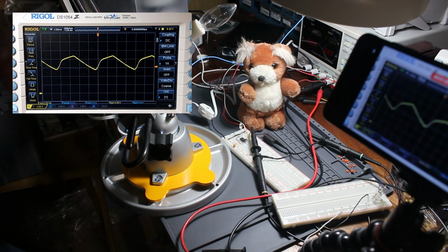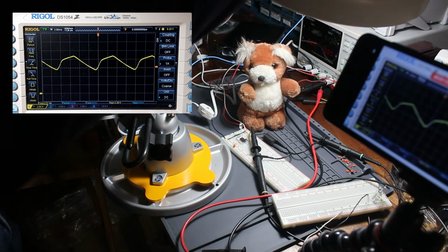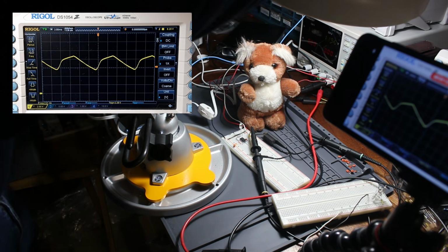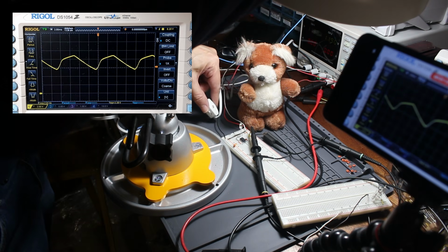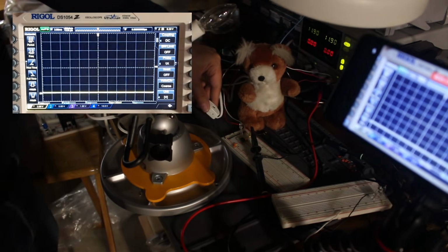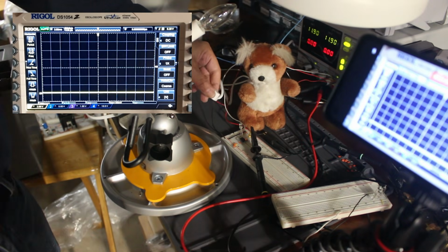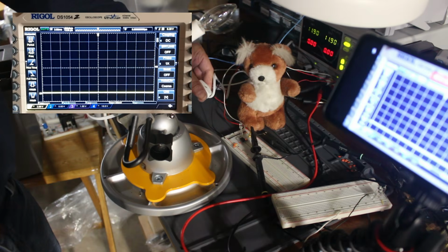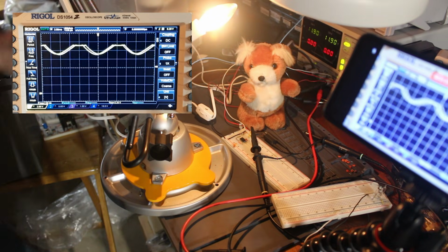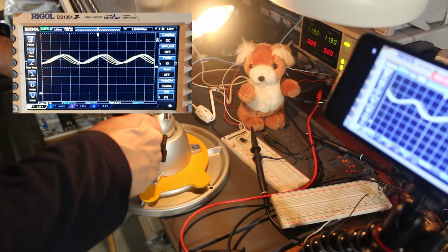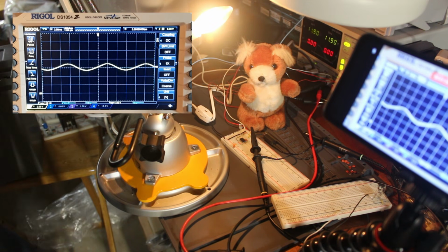I wanted to show something smoother, so I wanted an incandescent light. The only incandescent lamps I could find in the house were Christmas decorations, so I stole an electric candle from one of the windows. Oops, that bulb's a little too close to keep the output from saturating. There's still a little bit of 120 Hz visible, but the waveform is much more nearly flat than the other two sources. The filament is still hot for the entire cycle and gives off nearly a constant intensity.